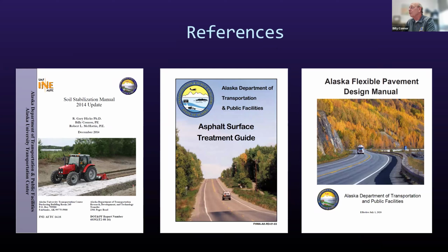These are some good resources for you. The soil stabilization manuals goes over a lot of ways to improve your aggregate and your surfacing. The asphalt treatment guide goes into the details of putting down either chip seals or high float, and gives you all the details for that. And for the high end is the Alaska Flexible Pavement Design Manual.